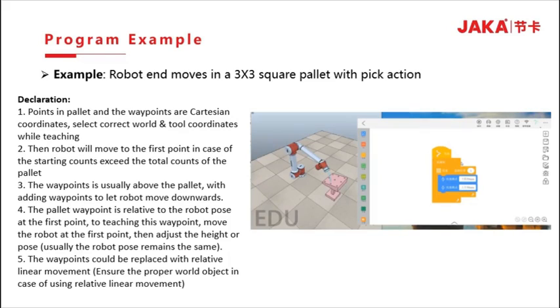Some more points about the pallet motion. 1. The pallet positions and waypoints are Cartesian coordinates. Be careful to select the correct world and tool coordinates while teaching.